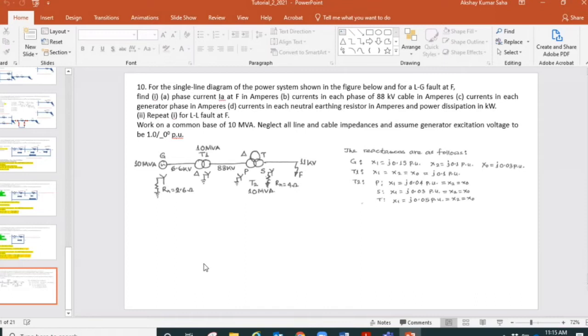And when it's three phase, we also need to make sure of the phase sequence that we talked about during the symmetrical components and symmetrical fault analysis. That phase sequence matters. So when you have two three-phase transformers, one is ABC, the other one also ABC. So A must be connected to A, B must be connected to B, C must be connected to C, or in other notation R, Y, B: R must be connected to R, Y must be connected to Y, and B must be connected to B. Again, the voltages must be the same.